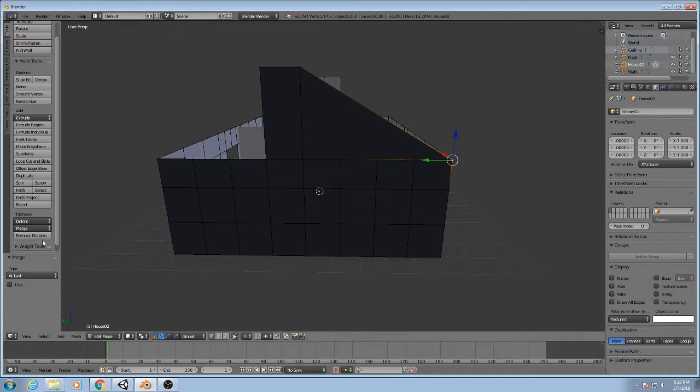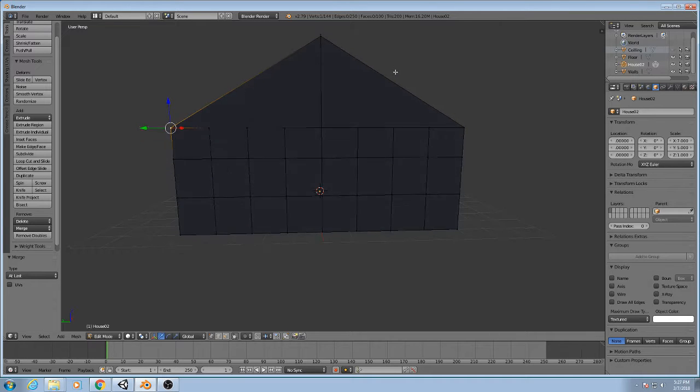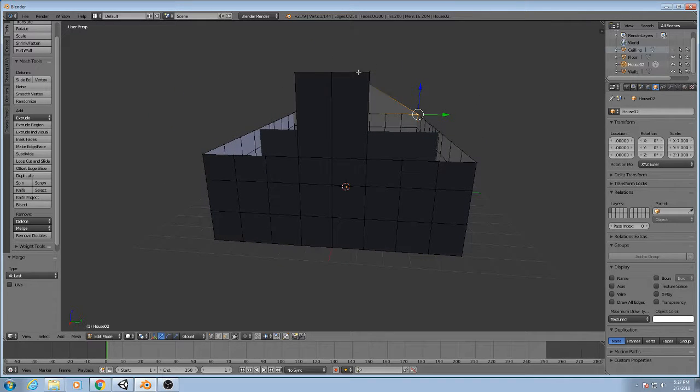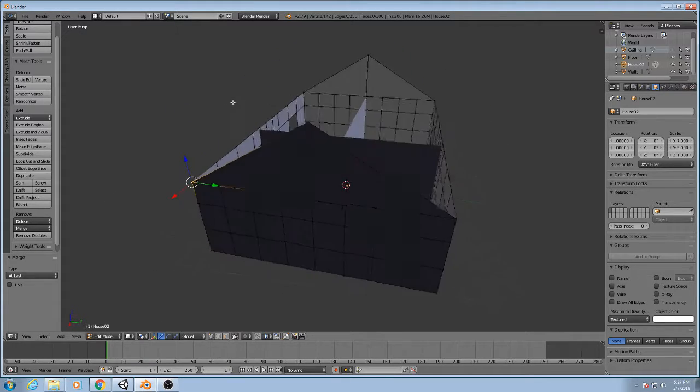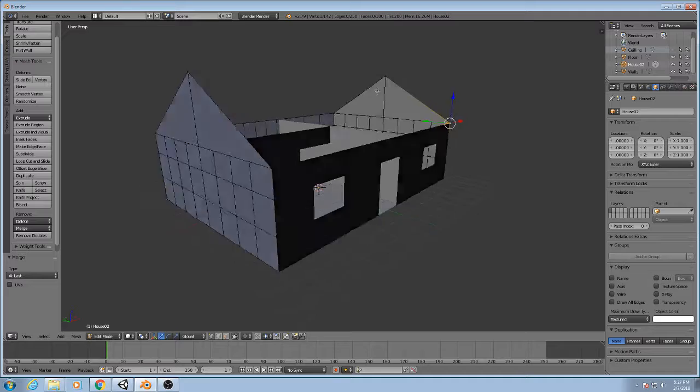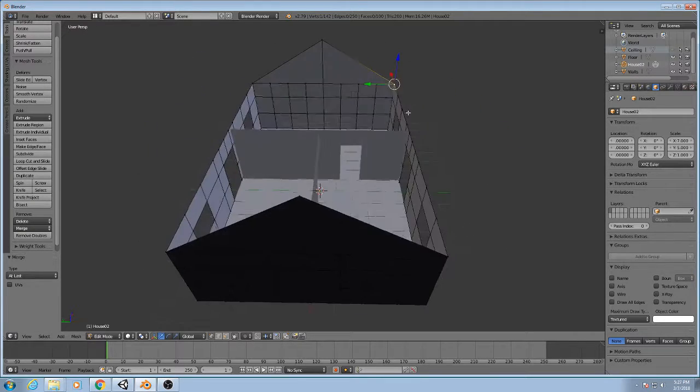So at last, see, click on this corner and this corner by holding Shift, merge at last, because we clicked on this corner last, and there's our triangle. Pretty cool, right? A simple, easy and productive way. So again, merge at last on this side of the house, and there you go. We have a pretty cool looking house so far, but it has no roof.